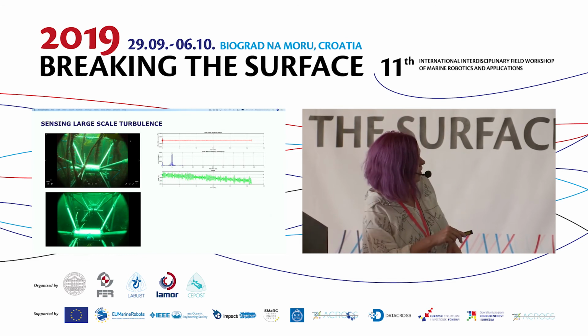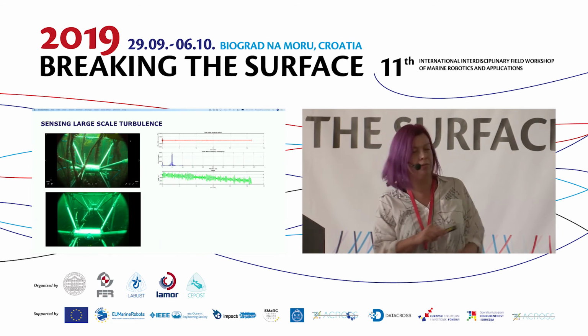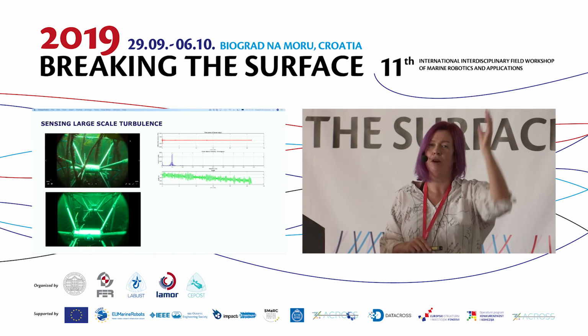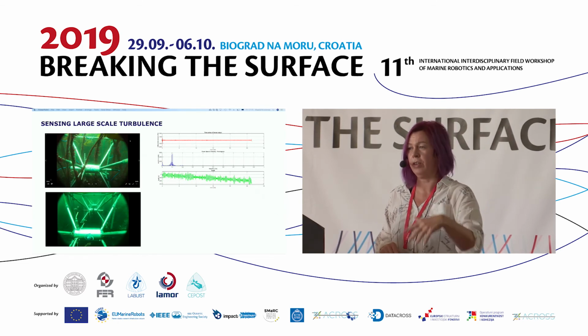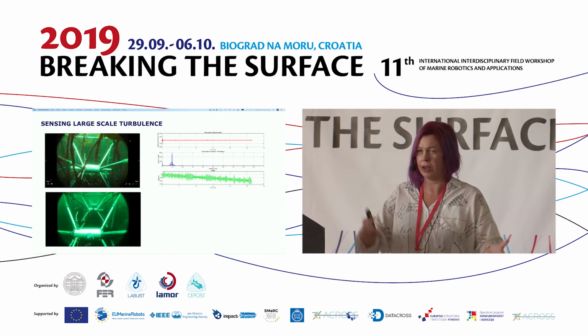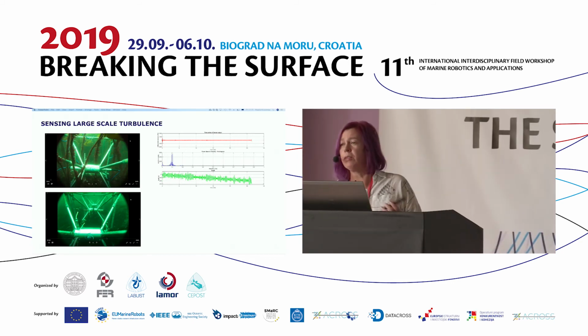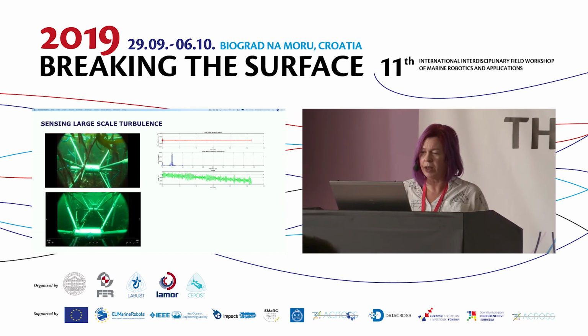But what's interesting here is that if you have a frame like that, with some sensors in the kelp forest and some above the kelp forest, you can also figure out how much drag is removed by the vegetation in the flow. You couldn't anyhow do it with acoustics because you would just get noise back. So it's probably the only way of understanding the dynamics of vegetation.